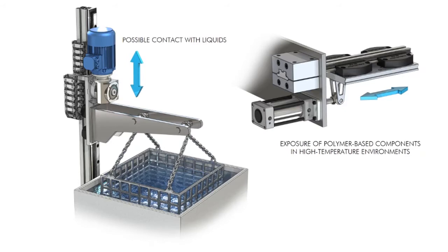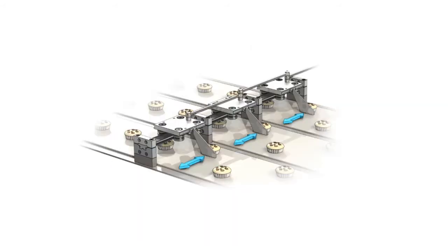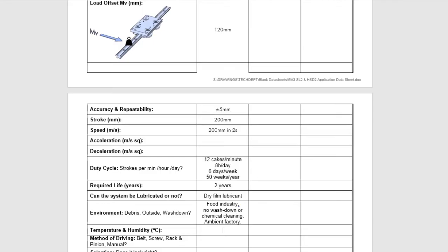In low temperature applications, grease can become more viscous, making it harder to move components. In these cases, there is the need to be careful with material and component selection. If these details are specified initially, provisions can be made to specify suitable materials for the application. In this application, the operating temperatures are ambient and dry.